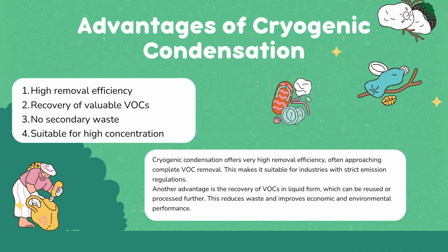Next, we jump to the advantages of the cryogenic condensation. There are 4 points here. The first one is the high removal efficiency. Next is recovery of valuable VOCs, the third one is no secondary waste, and the last one is suitable for high concentration. The cryogenic condensation offers very high removal efficiency, often approaching complete removal.